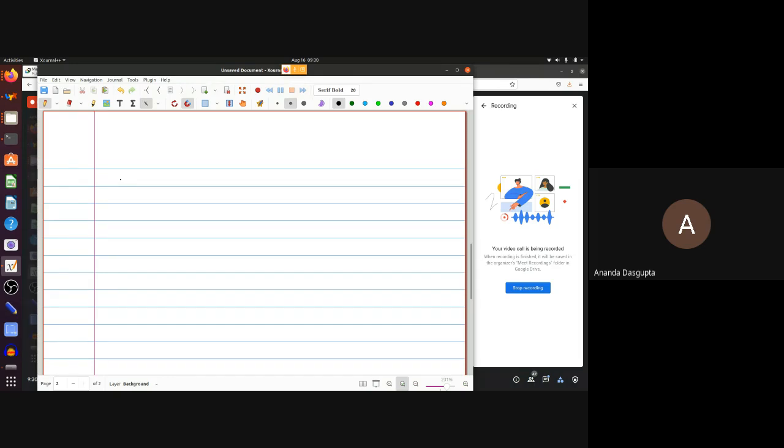Or actually, these models will help you to get a first approximation, but then you will have to change the quiescent point. So the curve might look very different. Suppose you have a V versus I curve which looks like this, and there are circuit components for which the V versus I curve does look like this. So the behavior here would be like a negative impedance. Here it would be like a positive impedance. Here it would be like something where the voltage is almost flat.